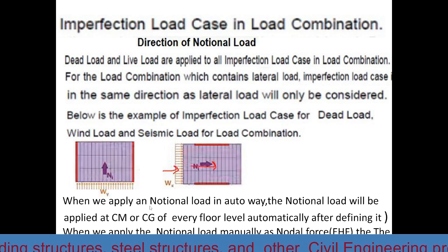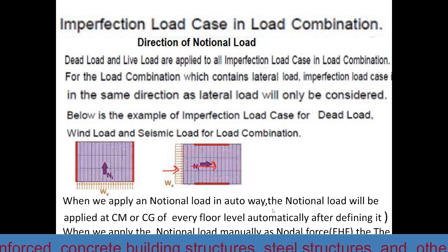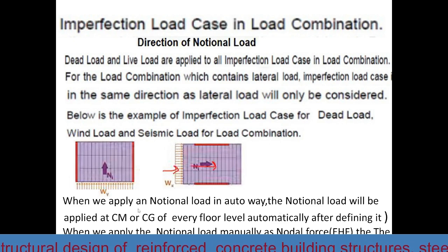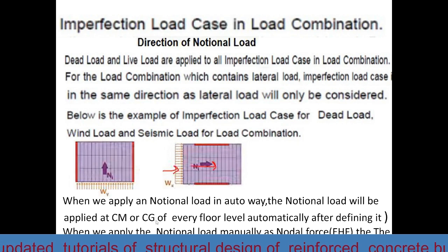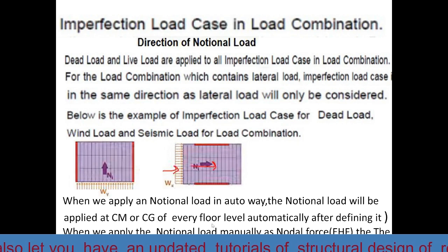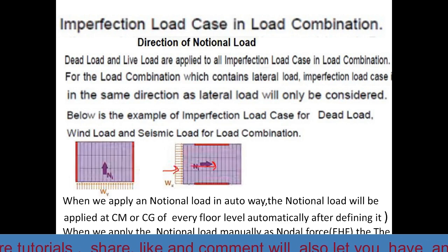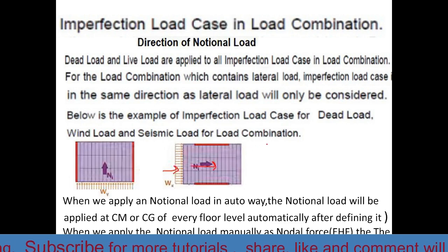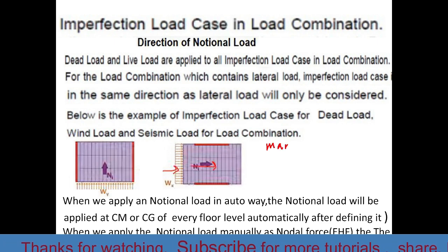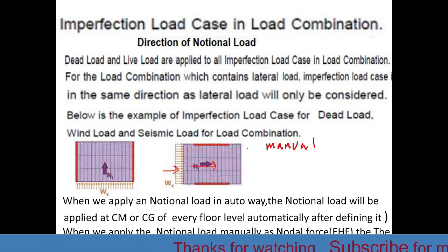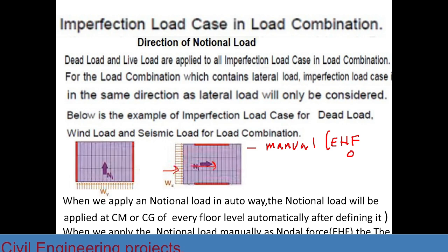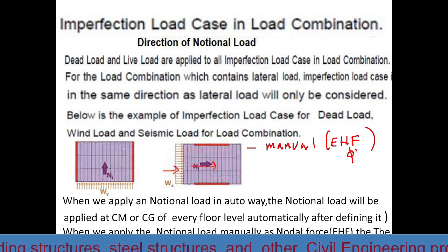When we apply a notional load in the automatic way, the notional load will be applied at the center of mass or center of gravity of every floor level automatically after defining it. So we can apply the notional load in two ways. One, manual application, that means just calculating the equivalent horizontal force, which depends on the vertical load.